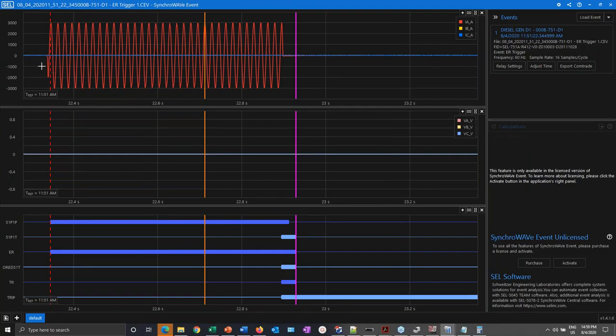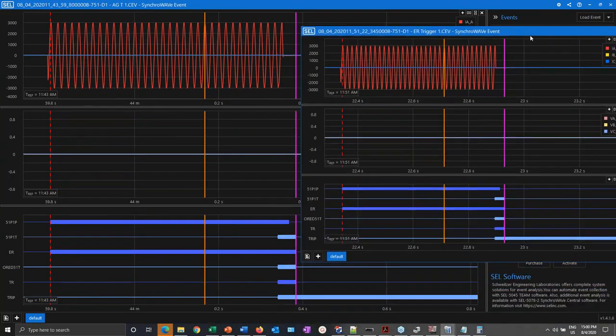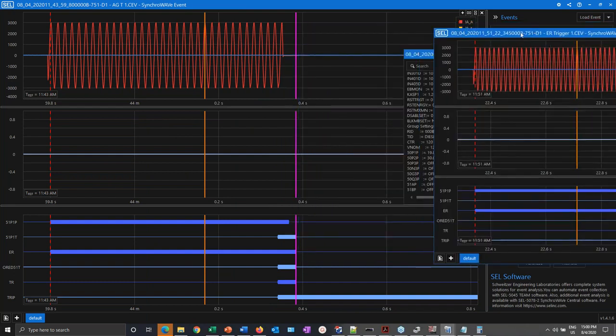The relay started recording here. It took 3 cycles before it recorded anything, because there was nothing, and then it recorded exactly what was being played back into the relay. But what is different now? Why does the one event give me a trip time that is about 15 milliseconds different?